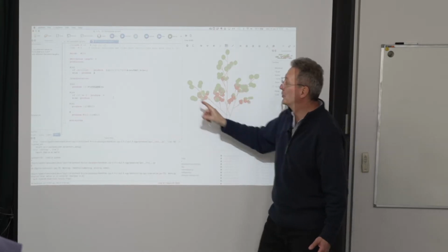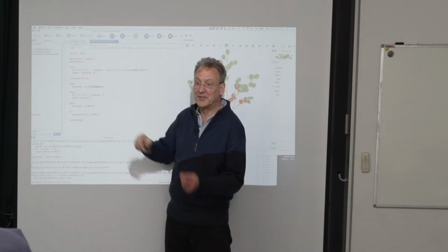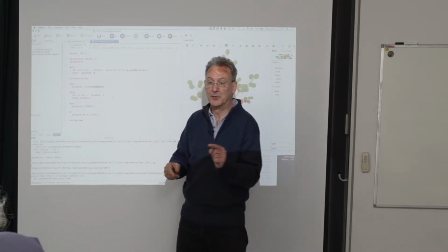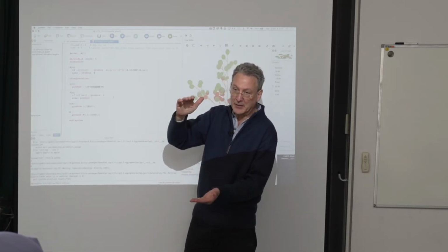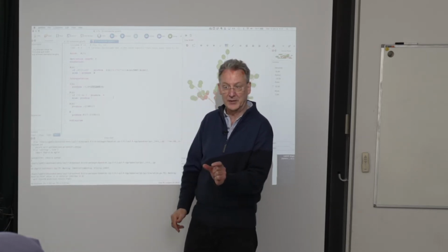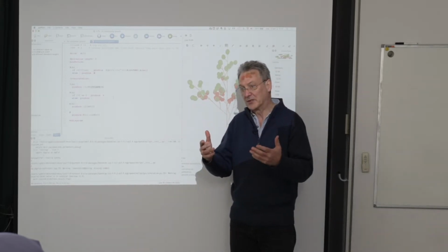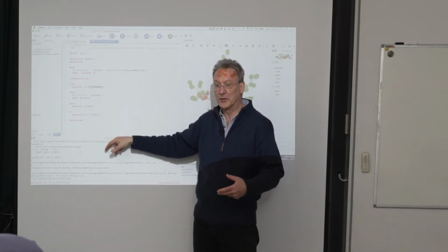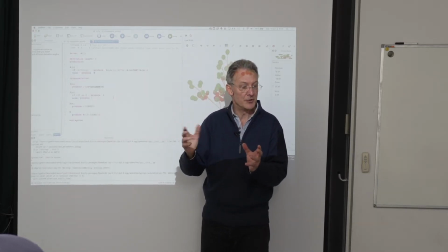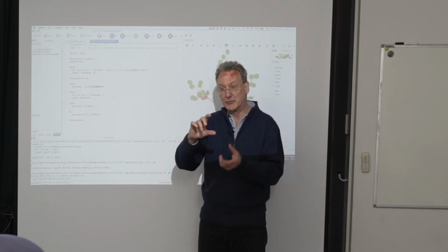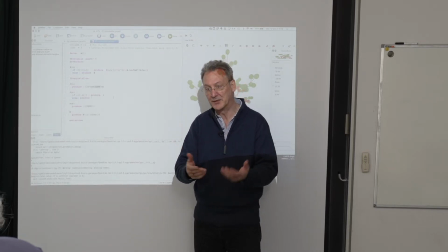So if I want to adapt the diameter to 15, initially by default it is 0.1 the diameter. So if I want to change the default, I need to put 1, and then it will be 15 of length against 1 in diameter. Okay? And this is always the case. Depending on the units that you use in your model, you need to adapt the allometry, which is the ratios between the different typical dimensions of your objects. So you need always to track this type of thing.